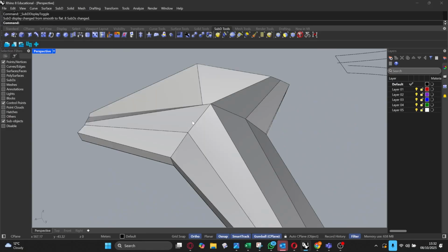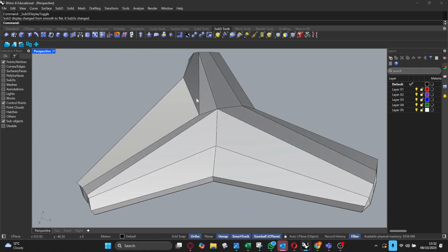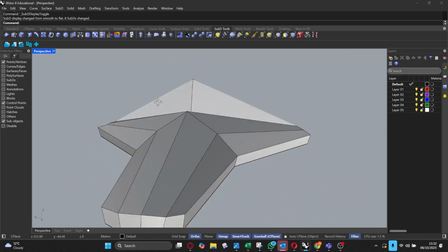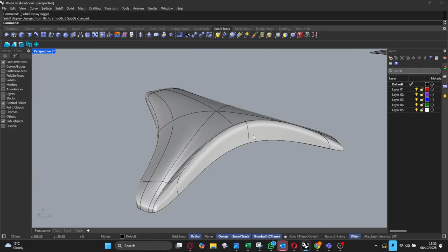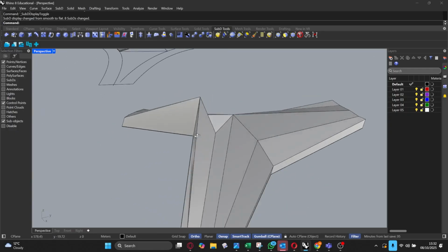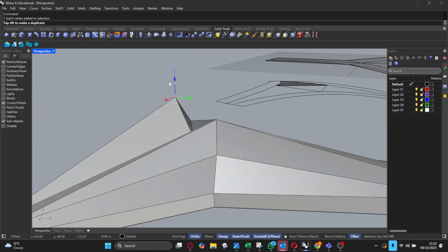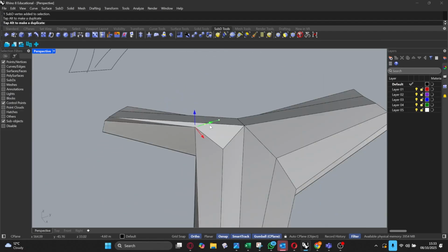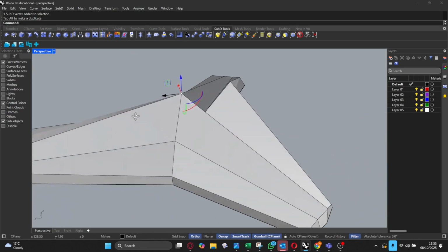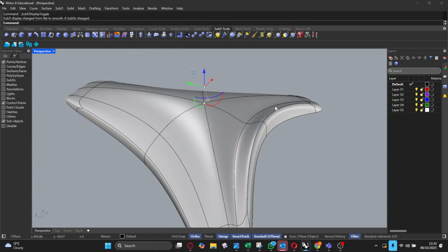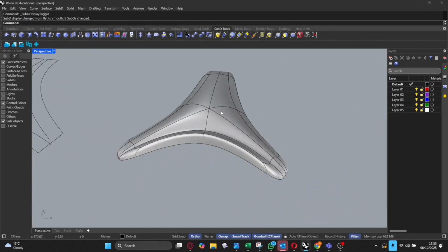Always remember what I said earlier. Look how awkward this object or shape looks now when I unsubdivide it. That's because I've been doing a lot of my moves when it was subdivided. So if I unsubdivide it and see that something is way off, I can play around with it and make sure that it looks and feels right geometrically in the unsubdivided state before I then subdivide it, and then I can start to play around with it again.